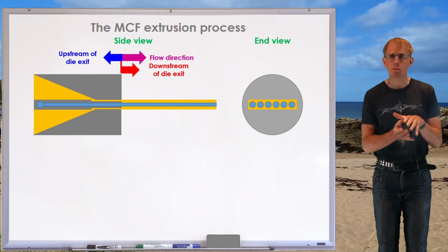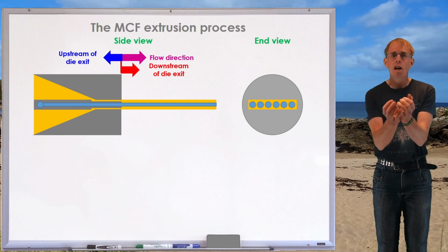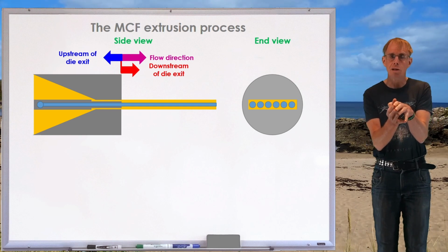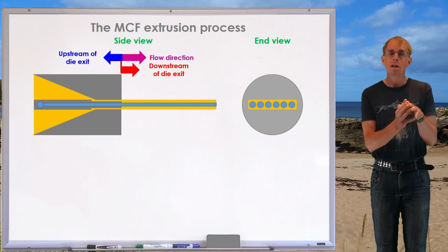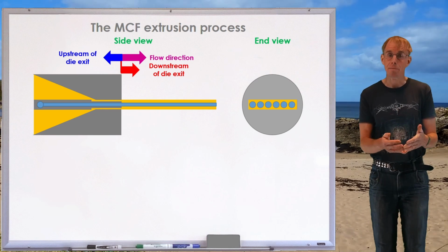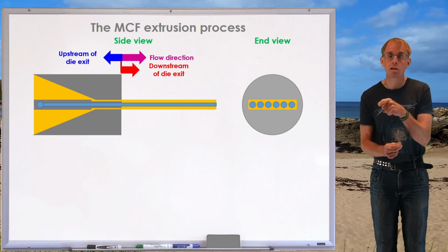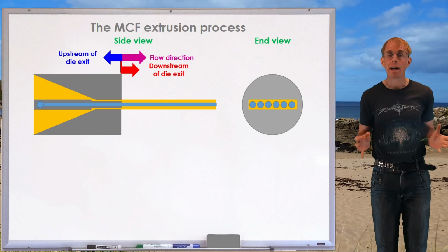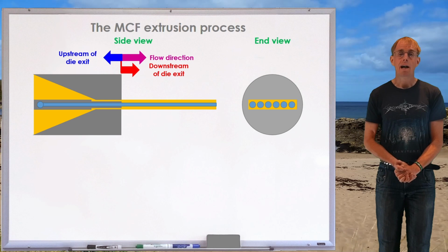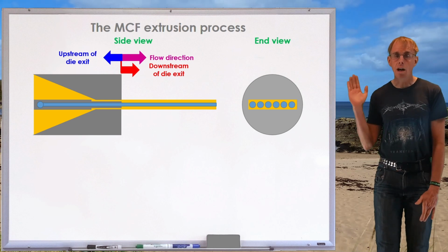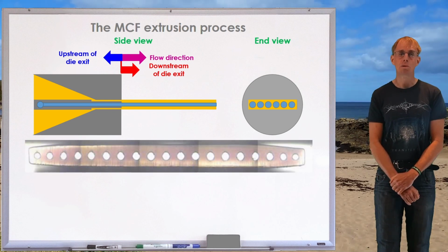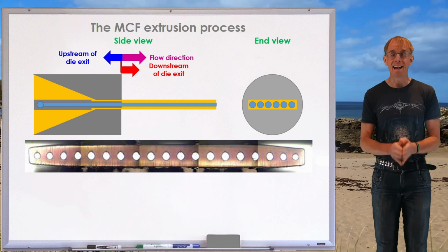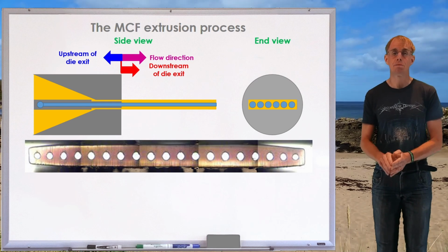Now, the action of the flow over these air injectors sucks air in as you get that change in direction over the injector tips. It causes a low pressure. That low pressure is lower than atmospheric pressure, and because there's continuous connection between the end of those injectors and atmospheric pressure, airflow results. And the sort of product that you get, I've put a picture of on the whiteboard. And it's great because it's a very elegant, very regular product.